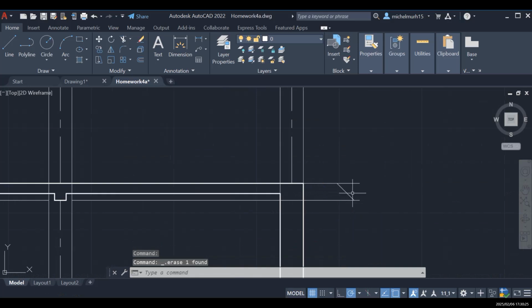So let me just delete everything again. Then I'm gonna go on here. I'm gonna start from here, for this intersection here, and then right now I'm gonna click on tab. I'm gonna activate the angle panel, and I'm gonna take 45 degree.